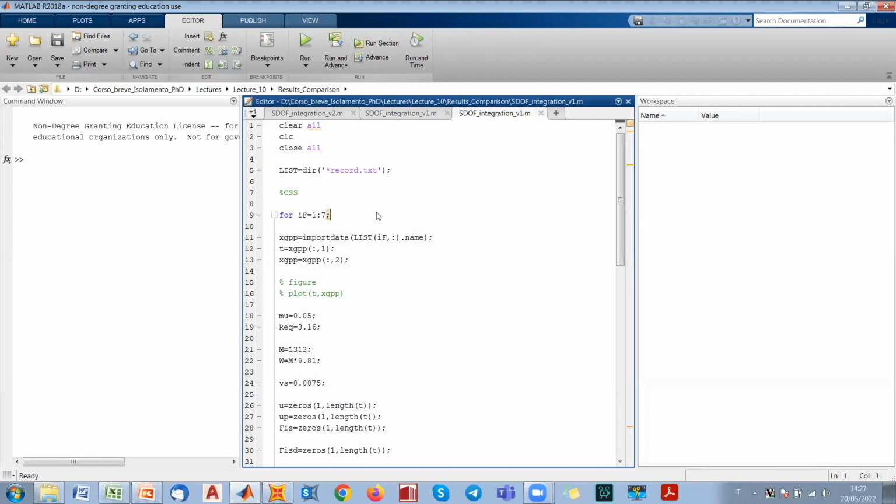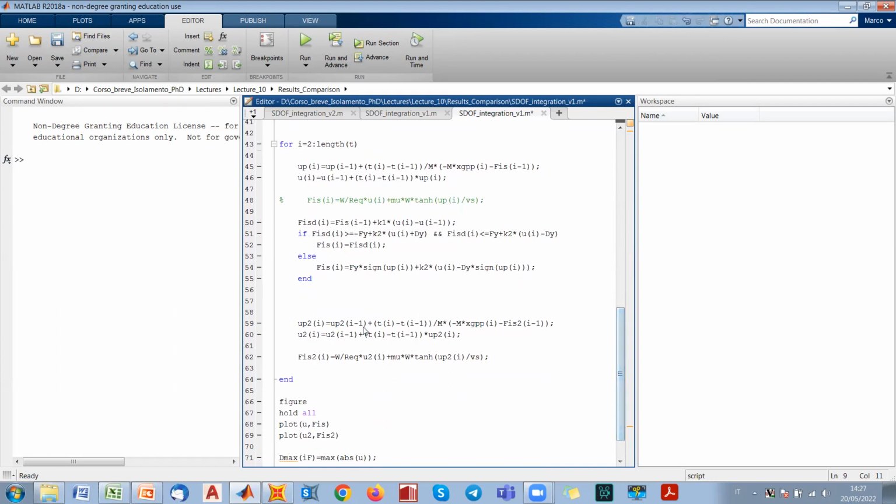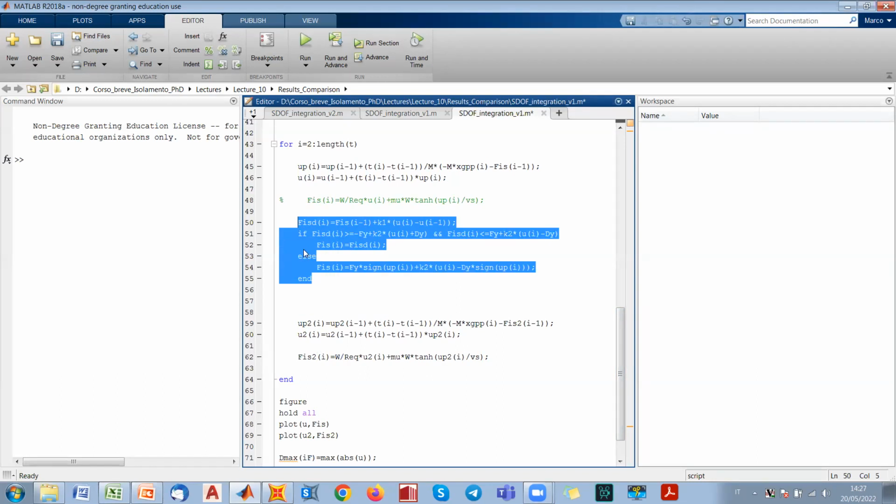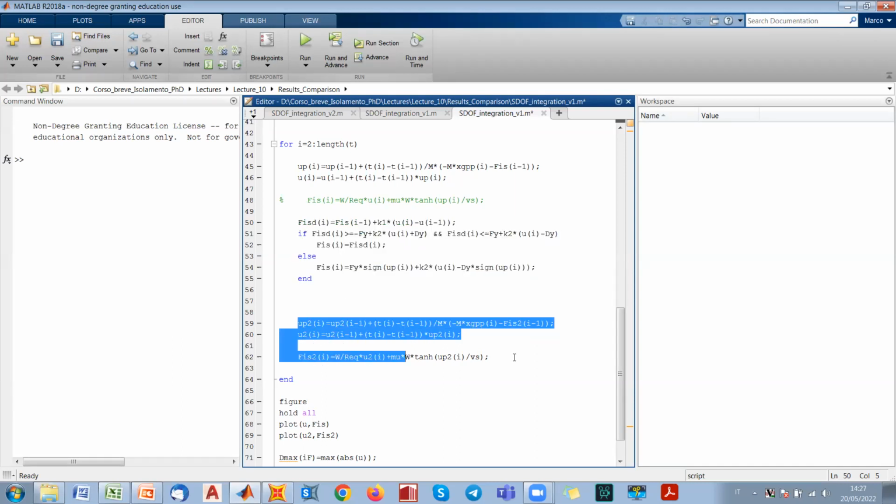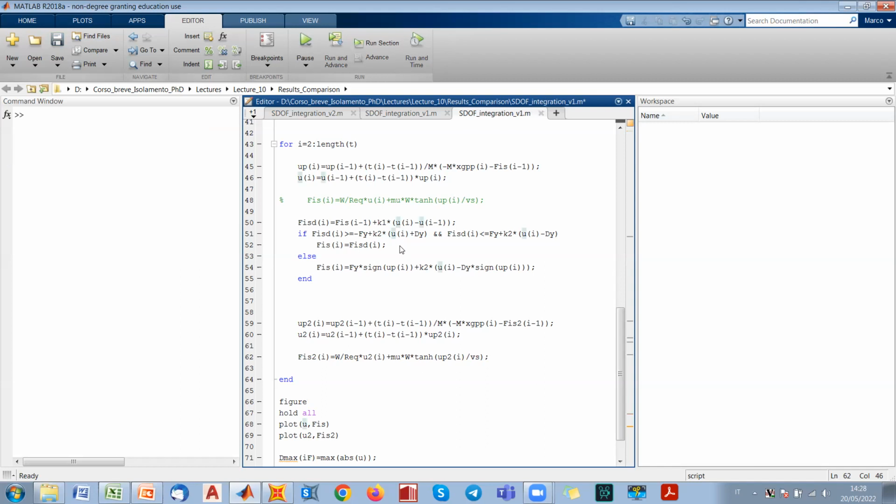And if you remember, we had 2 strategies for the implementation of the force response. The first one was the elastoplastic behavior with hardening, and the hardening is ruled by the recentering behavior. And the second integration method considered the force response as a function of the hyperbolic tangent of velocity, which is actually the force which approximates the sign of the velocity, but with a continuous transition through the 0 velocity value. So if I run these, we obtained the results that we got yesterday.